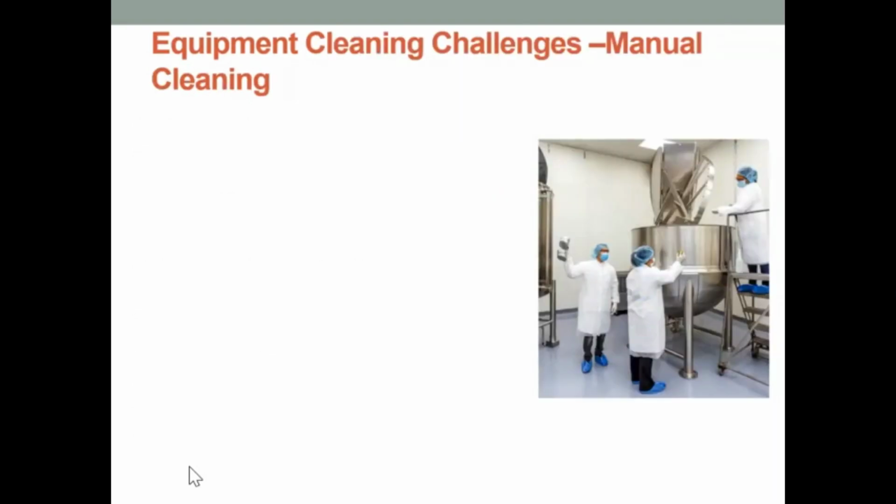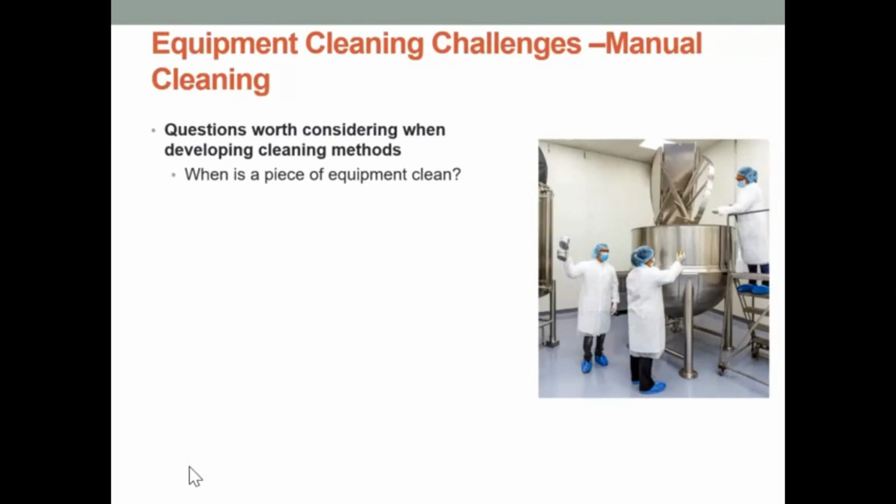Equipment cleaning challenges, so manual cleaning. Questions that are worth considering when you're developing cleaning methods. When is a piece of equipment clean? At what point can we stop cleaning? What is the definition of visually clean? Will all operators have the same understanding of it?